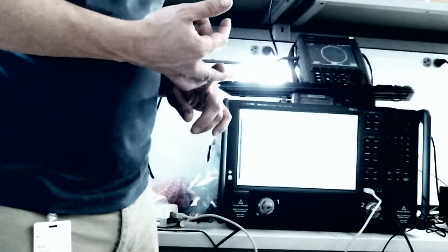So again, I have the option of doing a linear frequency sweep, a CW frequency sweep, or a segmented sweep. I can do power. Power is only going to apply for the S parameter portion. And what this does is it uses a cold source noise figure measurement technique. If you're familiar with noise figure measurement, usually it uses something called the Y factor. So the way that you do this is that you usually use a noise source. You guys may or may not be familiar with that.